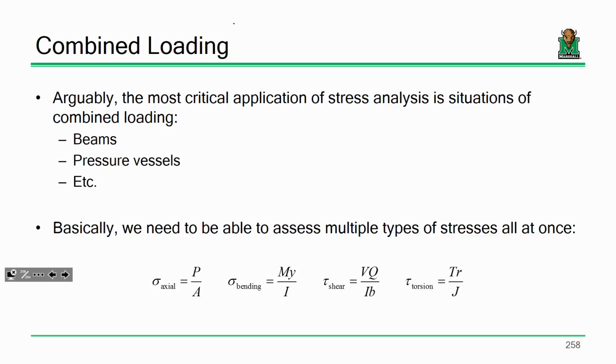Even if I give you an allowable axial stress and an allowable shear stress, you still can't theoretically determine whether or not it's safe because you've got multiple stresses acting at once. And from the Mohr circle discussions and the principal stress discussions that we've had, you know that if I just give you some stresses, under a given orientation those stresses can get worse. We went from 6 and 10 KSI to like 7 and 11 KSI. The stress bumped up. Maybe not a lot, but in some conditions they could really bump up. You see what I mean? So you have to understand that worst case orientation.